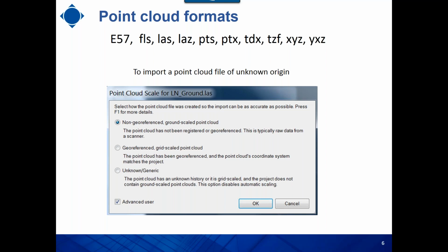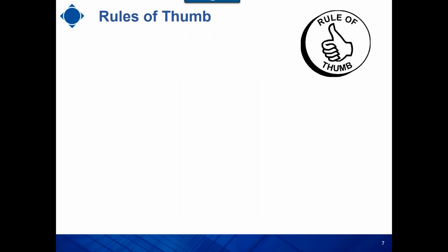And everybody here, you can join us at Cancel, and we have a lot of experience to help you understand how the point cloud should be imported. There are some rules of thumb that I wanted to put here. In order to make sure of an efficient import of the point cloud, always start your project with a template.